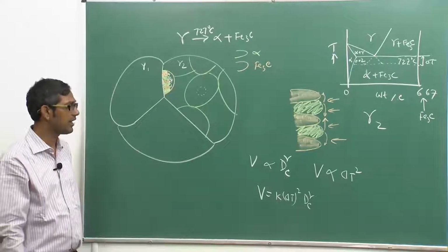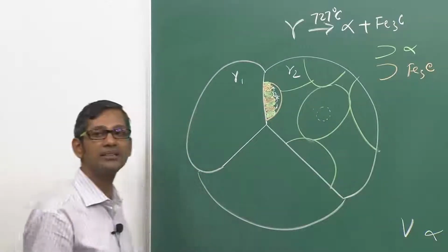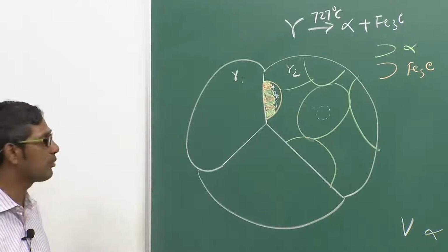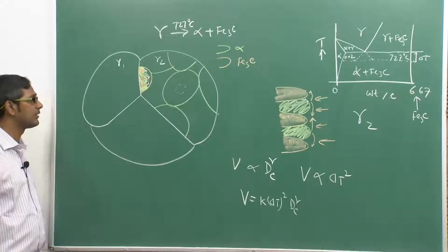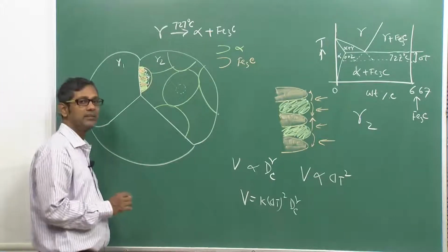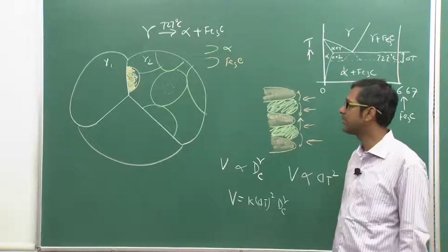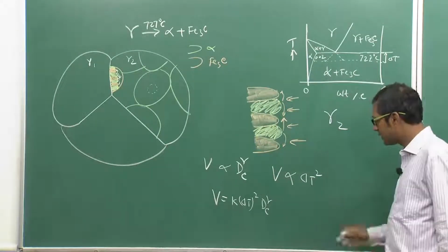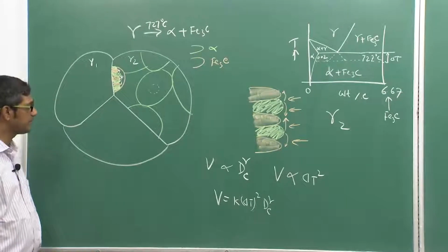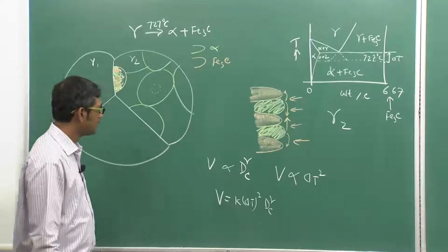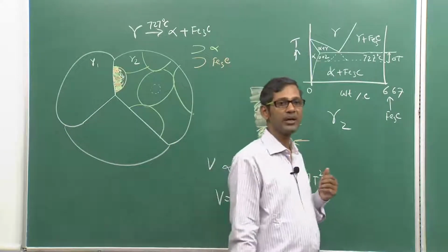Even if the carbon supply is very high, still the growth will be very slow, because it has to grow from inside a grain. So, therefore, nucleation requires larger undercooling. Nucleation will take away a large part of the undercooling, so the available undercooling for the growth will be much lower. That is another problem. So, the majority of nucleation observed in the literature does happen on the grain boundaries. That is one of the advantages of these solid state reactions. So, it is very clear that the diffusivity of carbon in gamma at a temperature close to about 700 degrees is quite high compared to others. So, that actually makes the pearlitic growth very fast. In fact, its growth rate should be a couple of hundreds of microns per second.